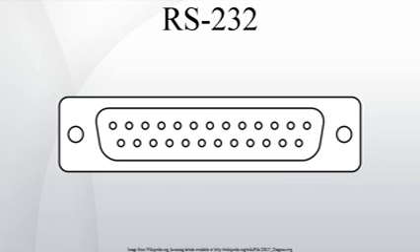Timing signals. Some synchronous devices provide a clock signal to synchronize data transmission, especially at higher data rates. Two timing signals are provided by the DCE on pins 15 and 17. Pin 15 is the transmitter clock, or send timing, ST. The DTE puts the next bit on the data line, pin 2, when this clock transitions from off to ON, so it is stable during the ON to off transition when the DCE registers the bit.